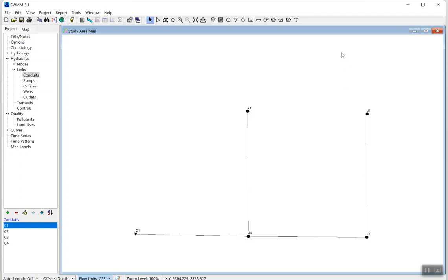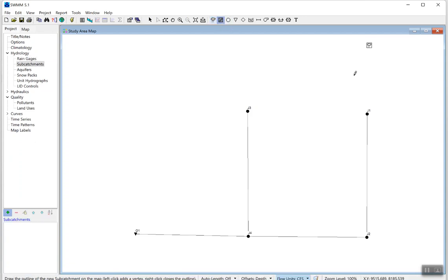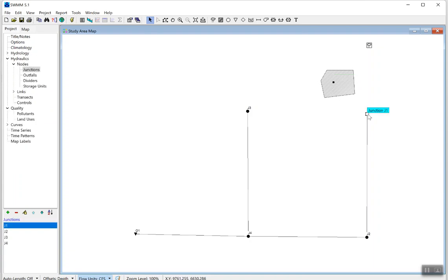The first one is by inserting a certain rain gauge like that, and a catchment like that, and connecting the catchment to this node. After receiving the rain from this rain gauge, there will be some hydrologic process and calculations, and then the amount of water that has been collected will be assigned to this node.